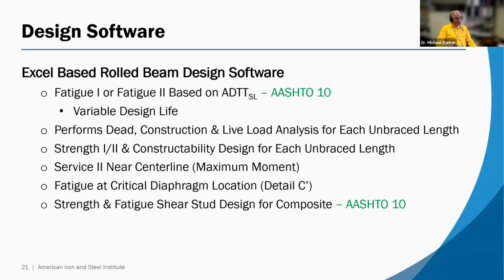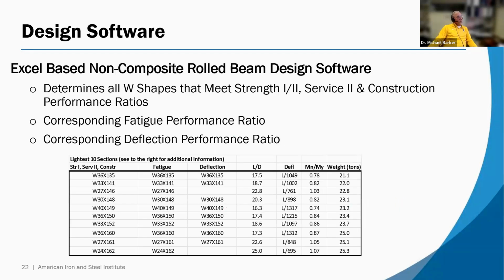And then we have fatigue, which we always have to be cognizant of. And it's going to check it at the critical location of a stiffener. And then if it's a composite bridge, it will do the strength and fatigue shear stud design for that bridge. And we're going to take a look at that now.